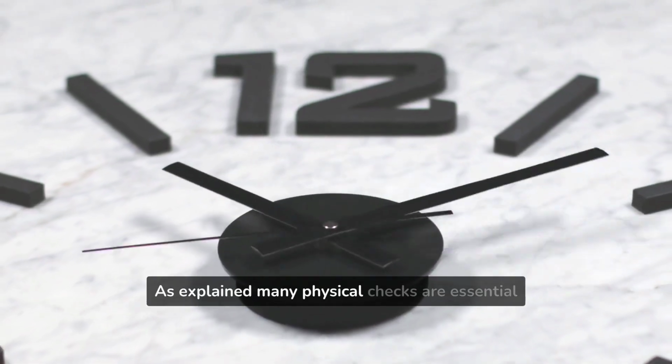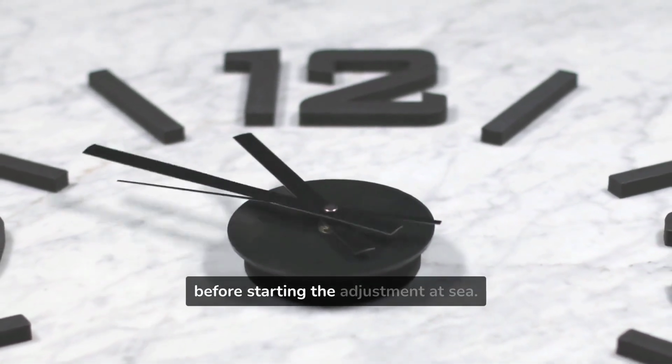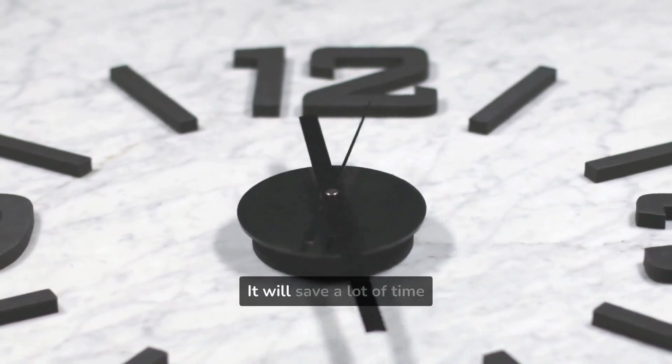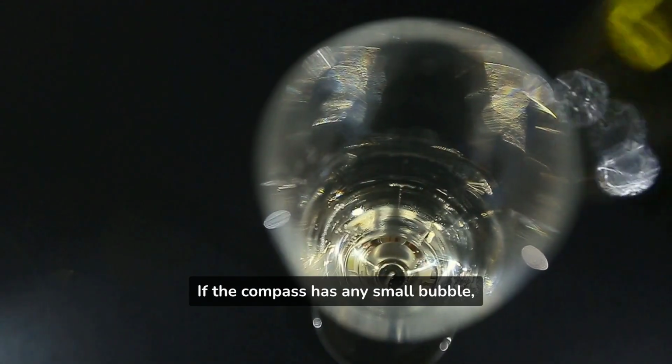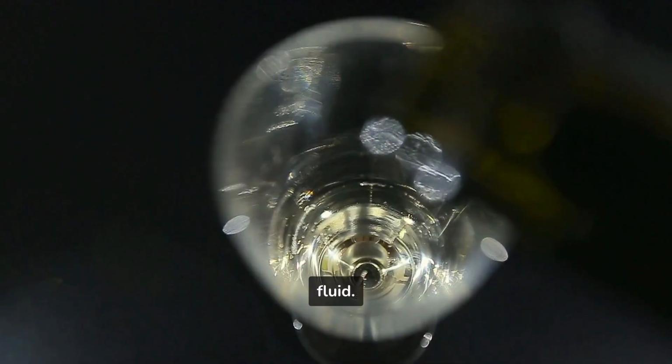As explained, many physical checks are essential before starting the adjustment at sea. It will save a lot of time and errors. If the compass has any small bubble, it must be filled with the proper fluid.